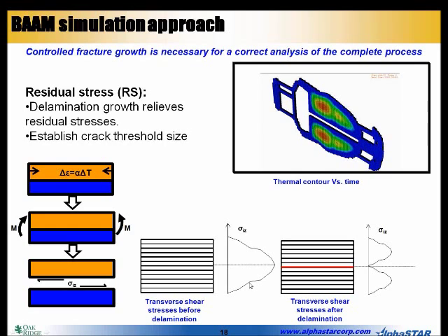And if you only look at delamination initiation, this will basically just start building up, and after the first delamination initiation that is occurring in the structure, anything after that becomes less reliable, because in reality, once delamination has been initiated, propagation of the delamination will also start, which means that the compatibility between the adjacent plies is removed, which results in a stress relief.